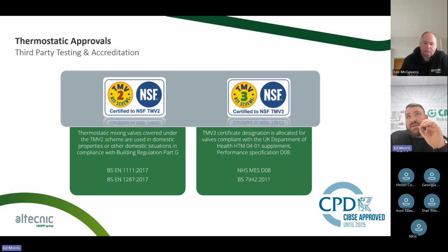A lot of the valves that you see on the marketplace are approved to TMV2 and TMV3. You will see some that are solely designed for TMV3. A lot of the differences between the two standards are under the fail-safe conditions. So where we look at when a valve fails, or when the cold water fails, we say how the valve will perform under those conditions. But those are the two standards you should always look out for.